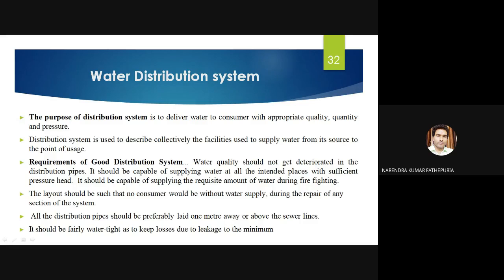community. While you're designing a water distribution network, two things have to be taken care of, in respect of the design period and from the service point of view. One is the losses should be minimized. The losses, including head losses, commercial losses, real losses, apparent losses, altogether should not cross 10 to 15%. Maximum 15% losses are acceptable in the distribution pipe network.